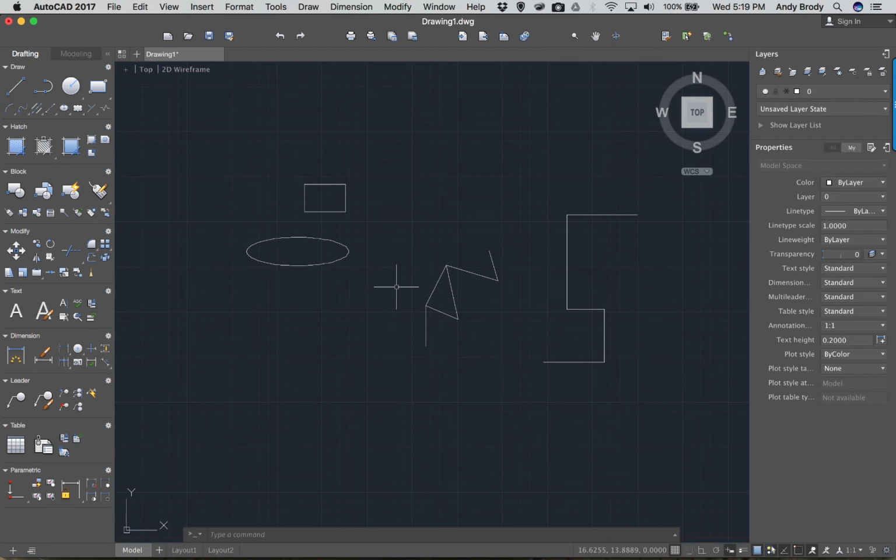Now, what I'd like you to do as you follow along here is to try out each of these basic drawing tools. Click on the line tool, click once to start the command, and once to stop it. Now, what you'll see as you draw, the cursor is still connected to that last point, and it is indicating another line is being drawn. That indicator is called a rubber band line. It connects the start point to wherever your cursor is. And you can keep drawing lines really until you click either another command or you hit the escape button.